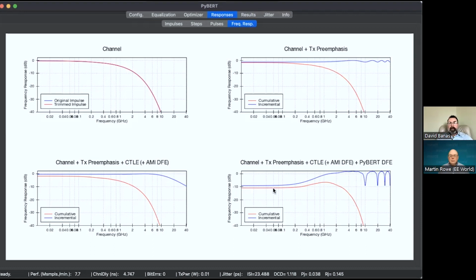And if you look at that point, in the raw channel, it crosses minus 20 dB at just above 4 gigahertz. So call it 5 gigahertz maybe. But in the equalized channel, if we look at where it's crossing minus 20 dB, we've pushed that out. You can see it's much closer to the 6 now than this one. This one crosses closer to the 4, and this one has been pushed out. Now, it may seem slight, but don't forget we're looking at a logarithmic scale here, both horizontally and vertically.